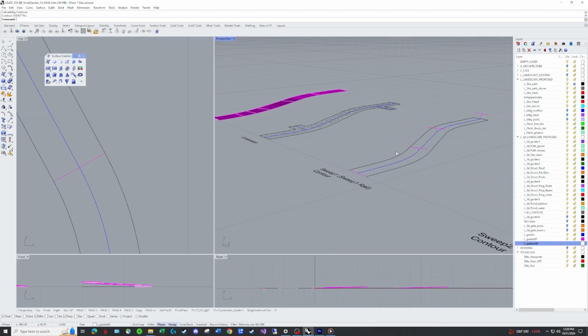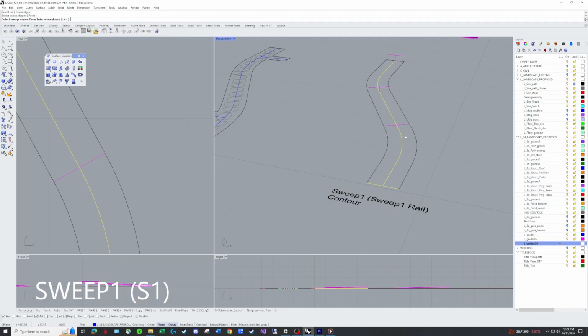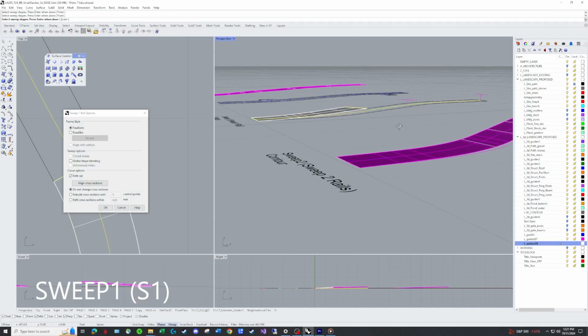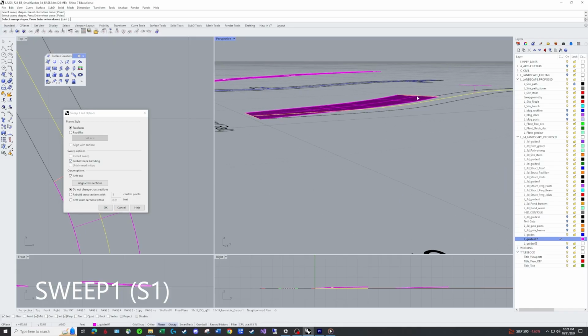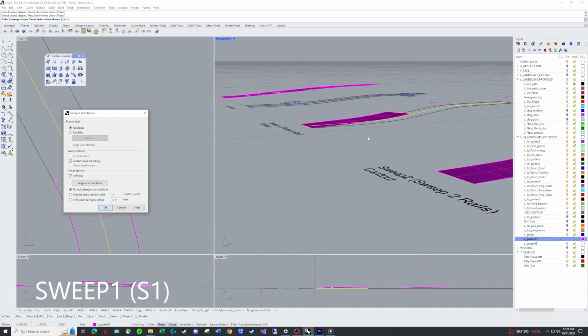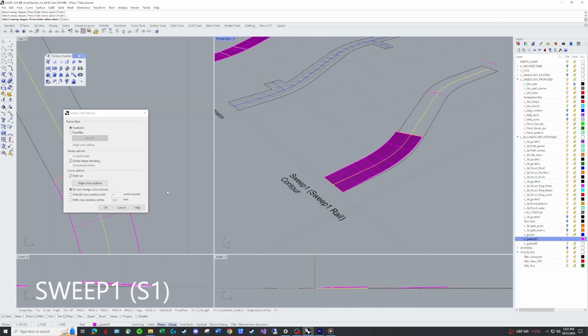And so if it gets a little bit wonky when you have global shape bending on, that's when you know you need to cut it into two parts. This isn't going to be bad though. I think sweep 1. I'm going to do the same rail, and I'm going to sweep from here to here. I'm just going to do this only. And go back to my layer here, and I need global shape bending. And notice the difference. Because it doesn't have to convert to this flat area, it can actually just make that uniform. It's not a hard geometry for it to do. So global shape bending is keeping you out of that parabolic language, and more into a straight uniform geometry. So I'm going to accept this, enter.